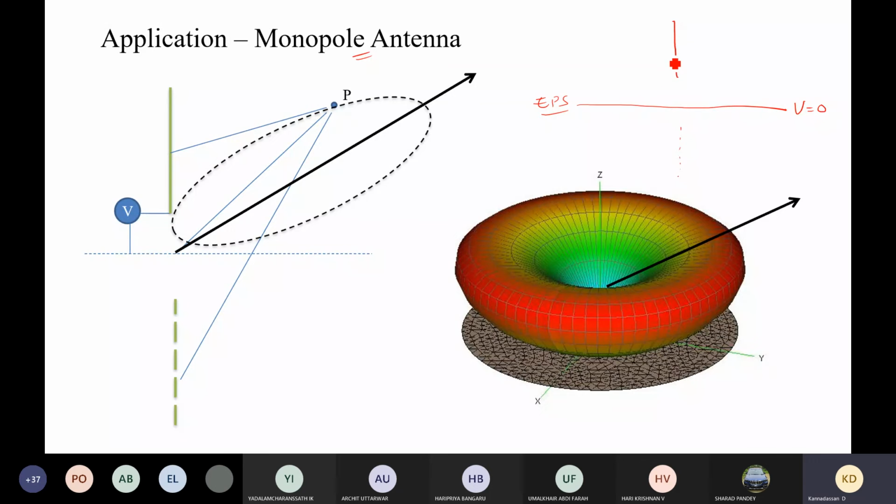So this is a simple dipole problem, positive and negative. Because of the line charge at any particular point, we know the electric field, that is E1. Because of the negative one, we have another electric field. If we add both vectorially, we get the resulting electric field. Interestingly, with respect to this equipotential surface, all this electric field will be available in this particular direction and not in the direction below, because below there is no real charge, so no field component will come out of that.